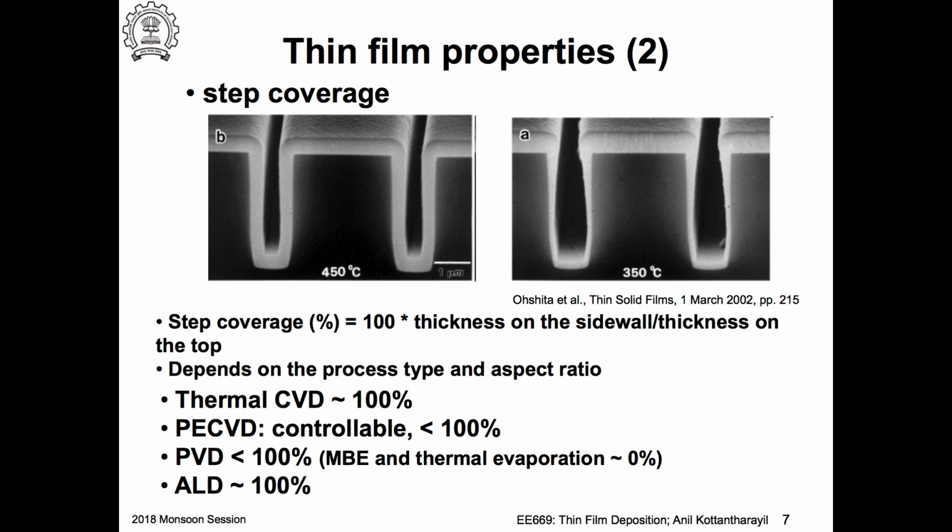Now, in this example, we have discussed that due to electromigration and series resistance and so on, if I am looking at metal, I would like to have a step coverage of 100%. But can you think of any process where step coverage of 0% is required?